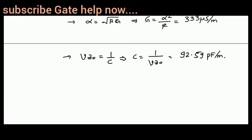And finally, V into Z naught is 1 by C. If you multiply the velocity equation and Z naught, I'll get 1 by C. So C is equal to 1 by V into Z naught. If you multiply this, you will get 92.59 picofarad per meter.